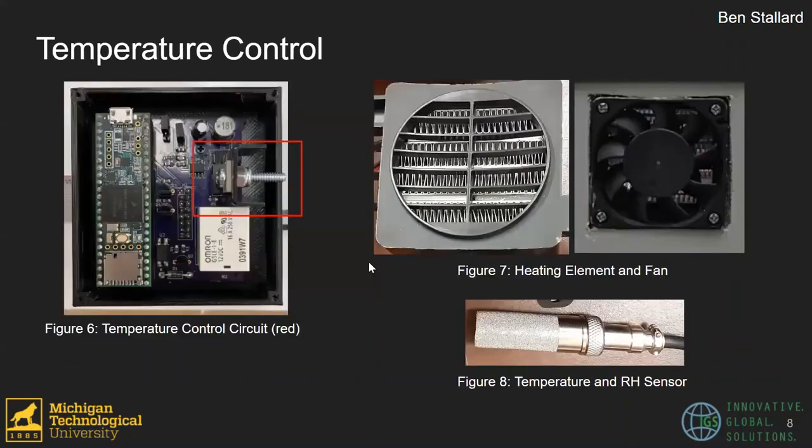Thanks, Morgan. The components of the temperature control system can be seen here on the slide. To the left is highlighted in red, the portion of the control panel that is responsible for regulating the temperature of the system. And on the top right are the heating element, as well as the fan that blows the heated air into the incubator environment. And on the bottom is the temperature sensor we use to gain readings about what's going on inside the incubator.